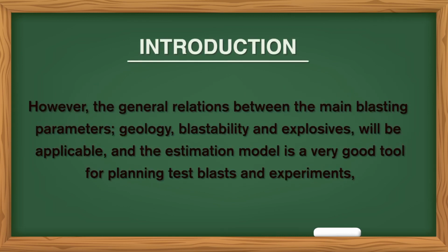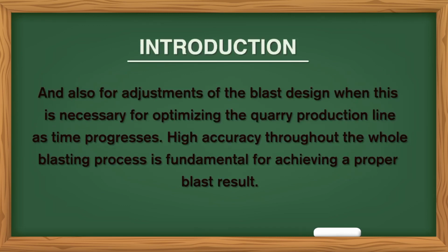However, the general relation between the main blasting parameters, geology, blastability and explosives will be applicable, and the estimation model is a very good tool for planning, test blasts and experiments, and also for adjustment of the blast design when this is necessary for optimizing the quarry production line as time progresses.